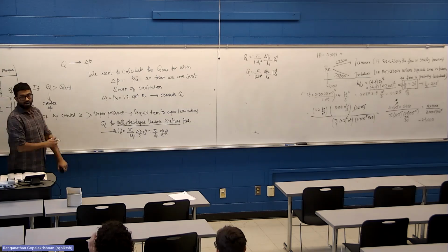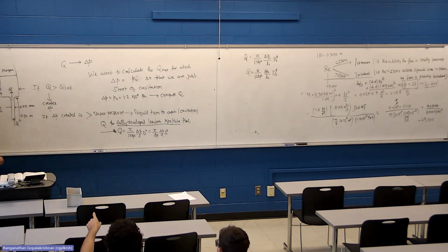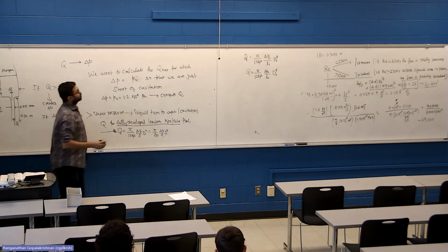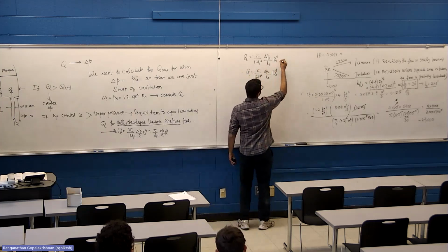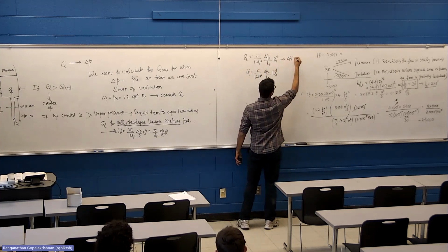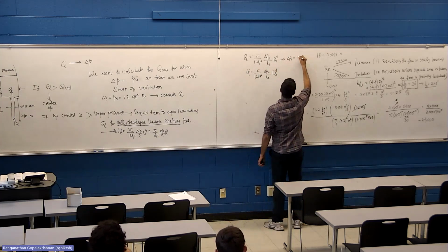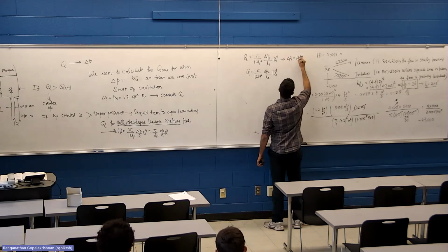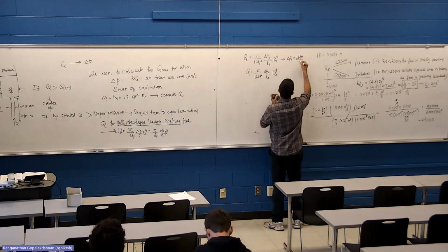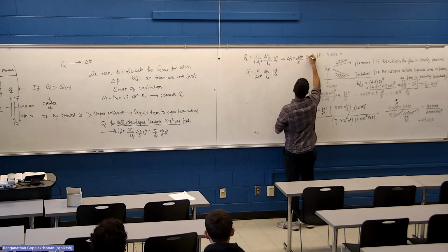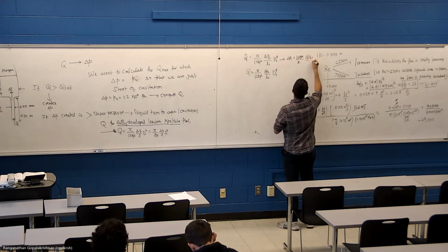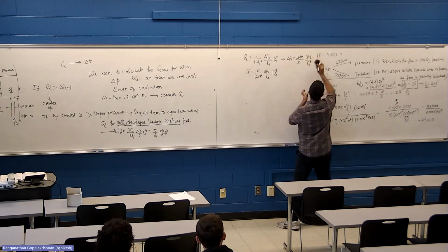So what you are doing is getting the part from the syringe and the part from the needle and adding them? That's the next step. I can take this equation and write the pressure drop in the first section as 128 mu divided by pi times Q L1 divided by D1 to the 4.